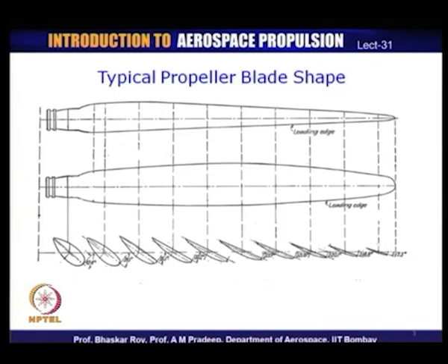Now, the aerofoil sections that we choose in these sections are essentially conforming to the local flow, as we have seen in the velocity triangles earlier. The local flow incident on the blade there is typically low subsonic, a combination of forward velocity, which we call V infinity, and the rotational speed 2 pi n r or omega r.